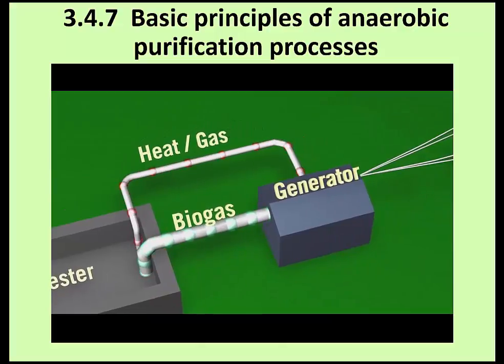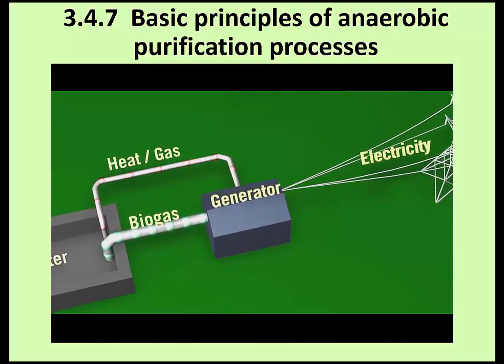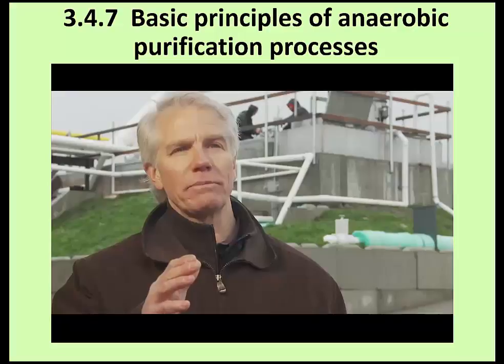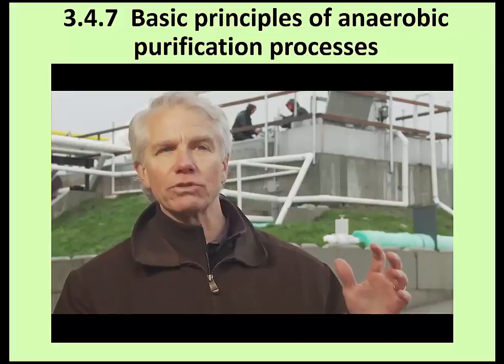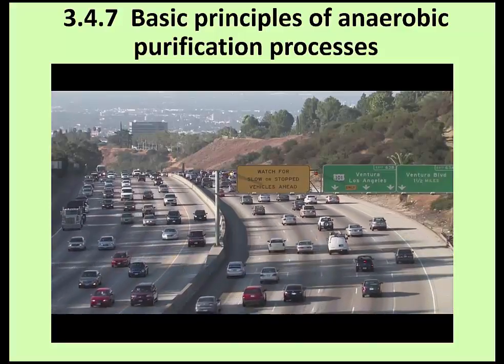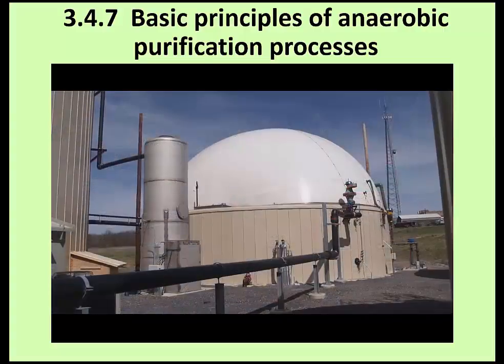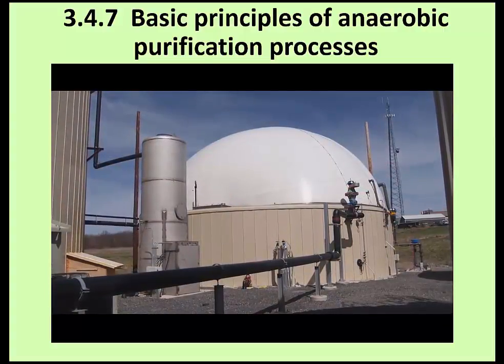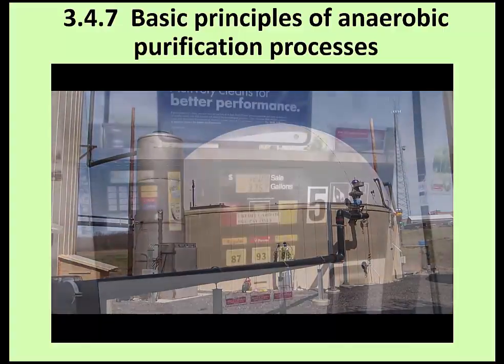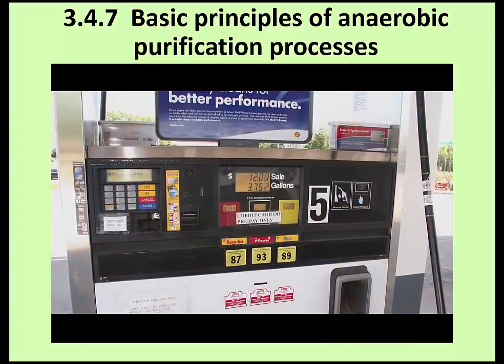Another add-on technology relates to the scrubbing and compression of biogas. In this type of system, biogas is converted to renewable natural gas fuel instead of being used to generate electricity. We're just in the middle of a shift from petroleum-based fuels to methane fuels, natural gas for trucking fleets and for cars. We have the technology now to produce renewable natural gas from the biogas that comes off the digester. It's clean to pipeline standards, and is available for vehicle fuel for half the price of diesel.